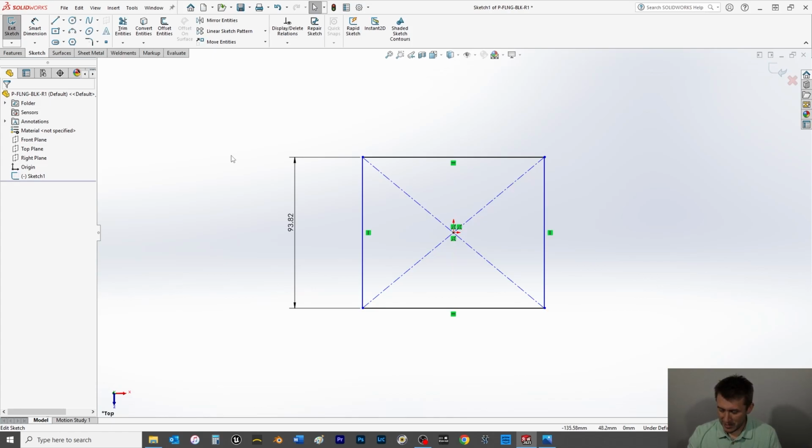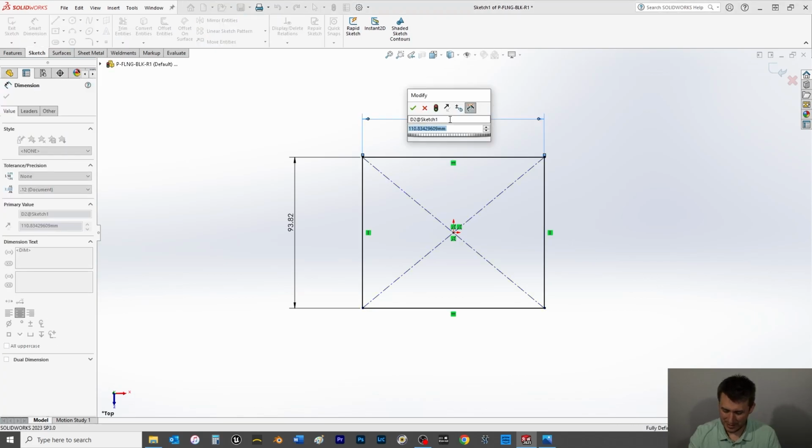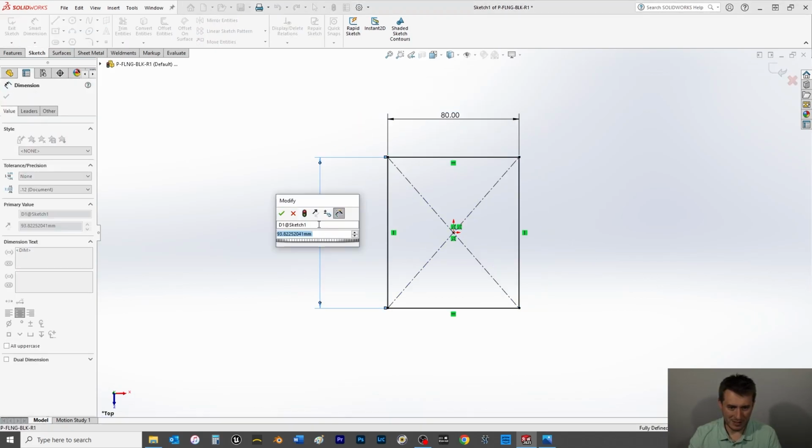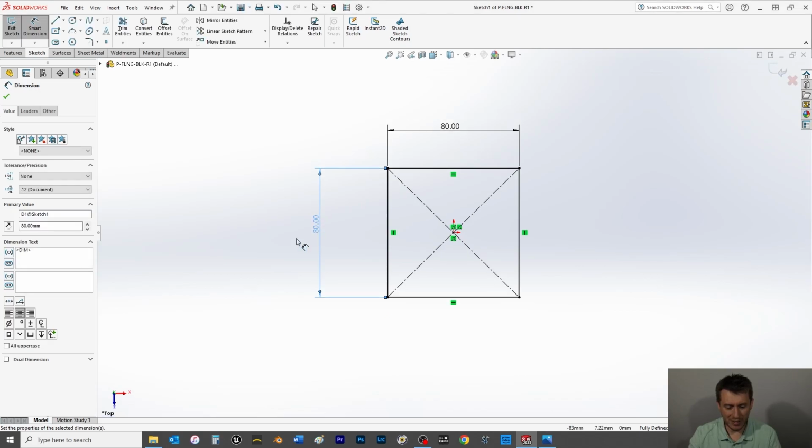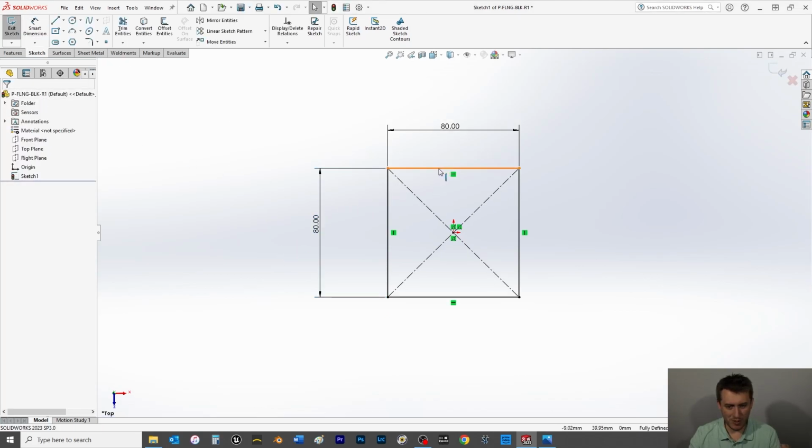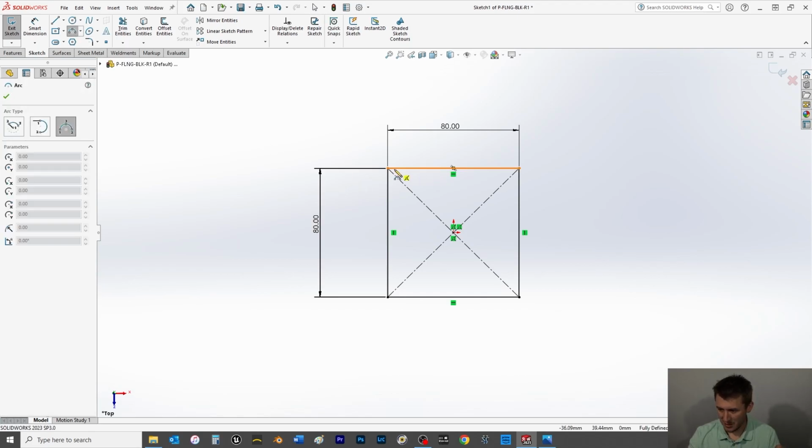Okay, so let's see, radius 40, that's a diameter of 80, so that center point is 130. There you are, 80. So this is 80 mils. So it's 80 by 80. Scan my layout here. Okay. Now technically I could have done it with just one dimension, making it equal to, but just in case, kind of a verification here, I want to make sure of that.